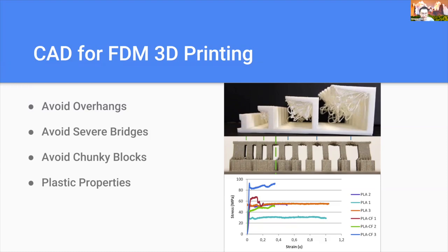the filament extruded, the melted plastic, does not get cooled fast enough in a sense that it will be able to stay in shape in midair, right? So you can see that there's kind of like a spaghetti formation on the bottom of the overhang, and that's what happens when the plastic doesn't cool fast enough. It essentially drops.